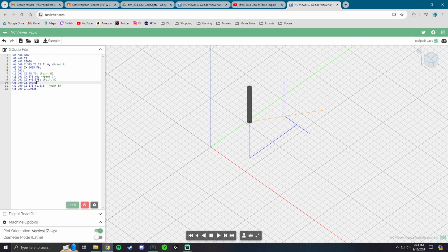So whenever you have to go up and over, so kind of this motion, finish my first letter, up, over to the next point and go down, you should always be doing these G00s. These are going to be a rapid movement up and over to get there as fast as possible. So later on, if we do some more practices or anything with mazes and stuff like this, this pattern of G00, these 3 lines are going to be very, very important. So I'm going to go ahead and leave you with that, and hopefully this video helps for you completing the activity on relative code.